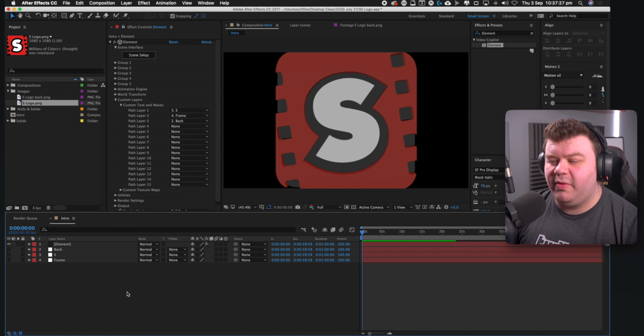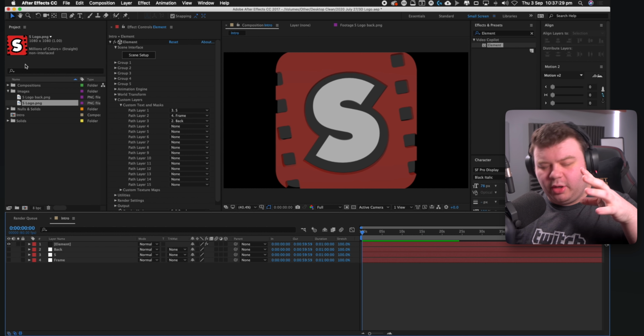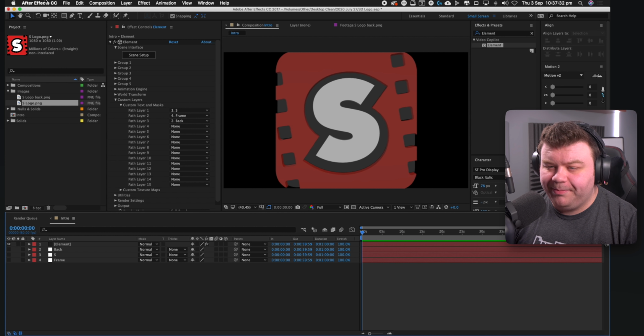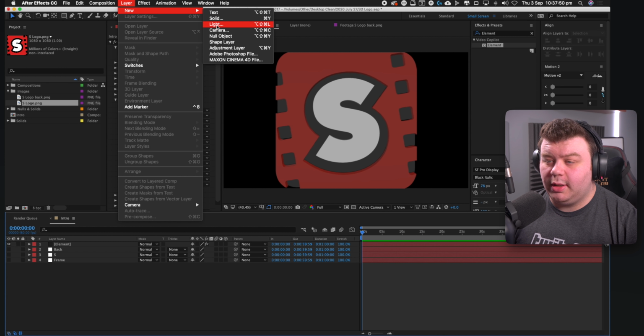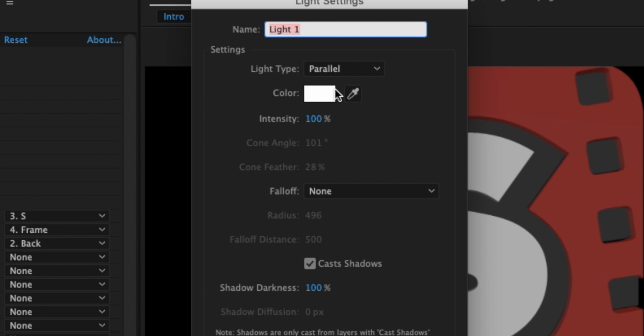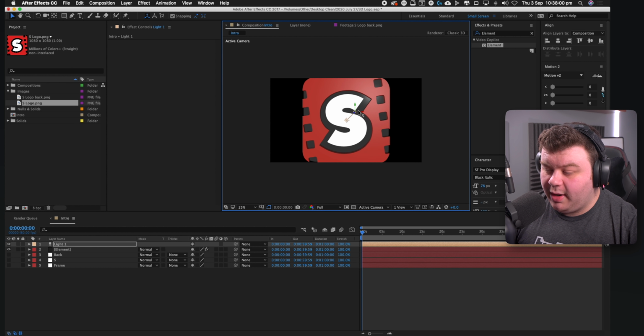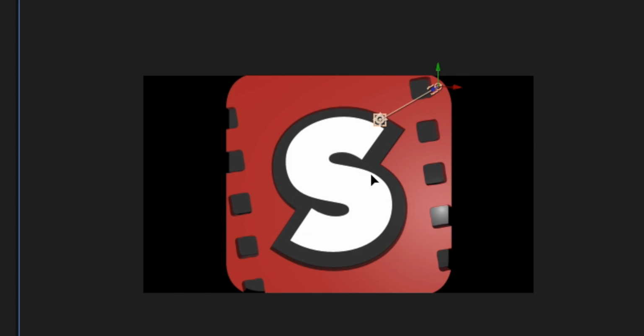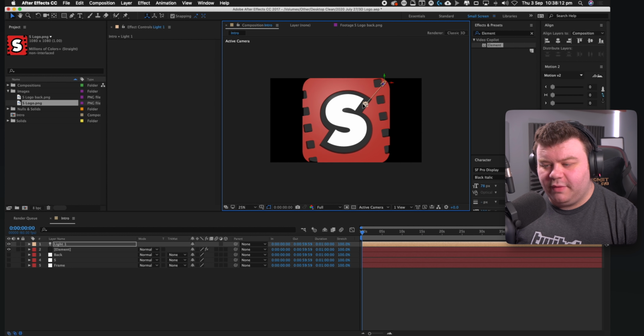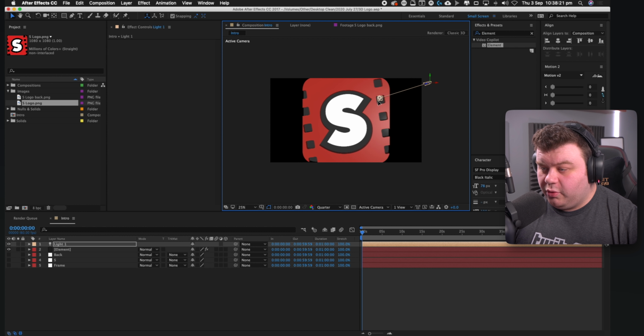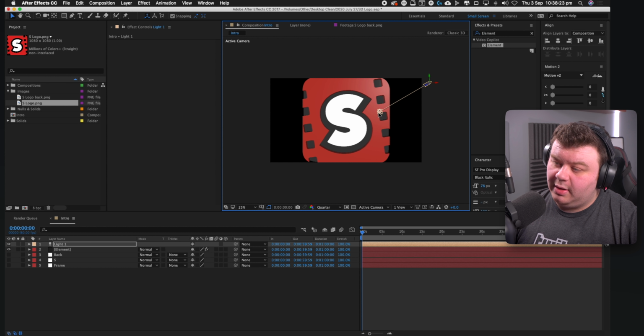And now we're going to work with the lighting and getting everything looking nice and getting our lighting in the right position we need it to be in. So I'm going to click on Layer, New, Light. And what I'm going to do is make it a parallel light with an intensity of 100. And I'm going to click OK. When we put that in, you instantly get some light effects right here. I'm going to play around with the position and the angle of the light. Imagine this dot here as the angle the light is facing. As you can see, if I rotate it and play around with it, we're playing around with the angle of the light and how it works. Put it in this corner right here, like that.